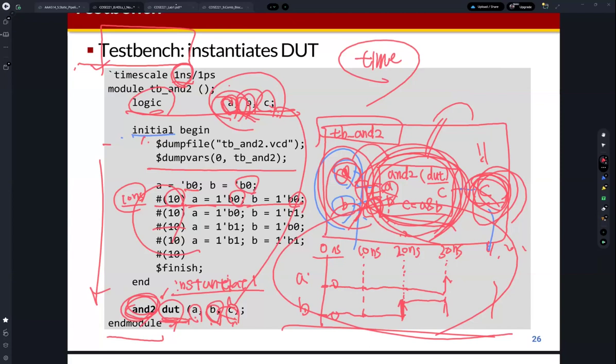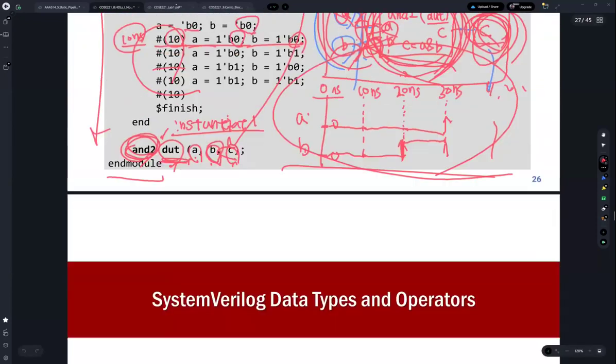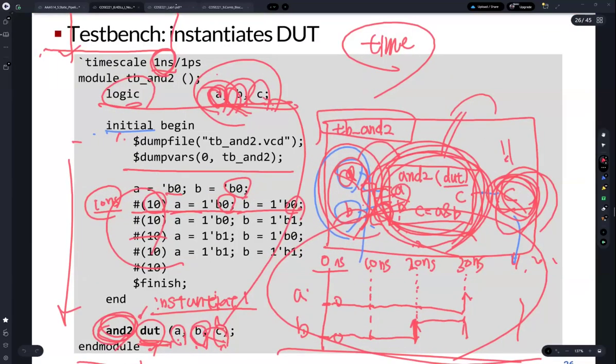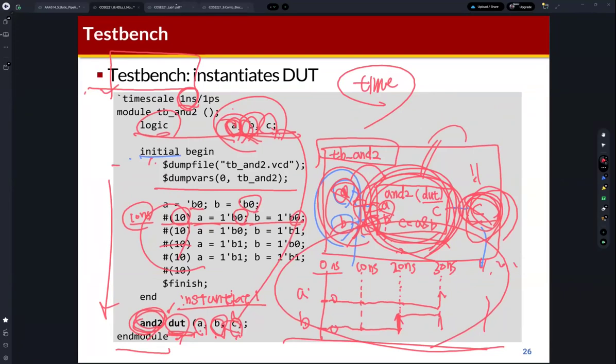Your report can include the actual waveform. By doing this first lab assignment, you can practice the verification flow using the HDL tools. We use Icarus Verilog, which is the HDL compiler, a compiler for SystemVerilog, and then we use GTKWave, which is the waveform viewer.